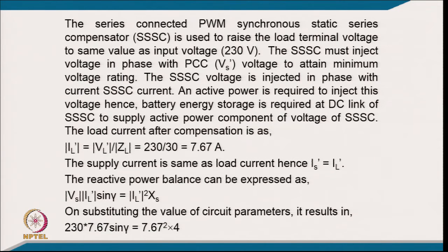So, a series connected PWM synchronous static compensator is used to raise the load terminal voltage to the same as the input voltage of 230, and the SSC must inject the voltage at the PCC to attain the minimum voltage rating. The SSC voltage is injected in phase with the current of the SSC, and active power is required to inject the voltage. Hence, the battery at the DC link of the SSC is required to supply the active power component of the voltage of the SSC.